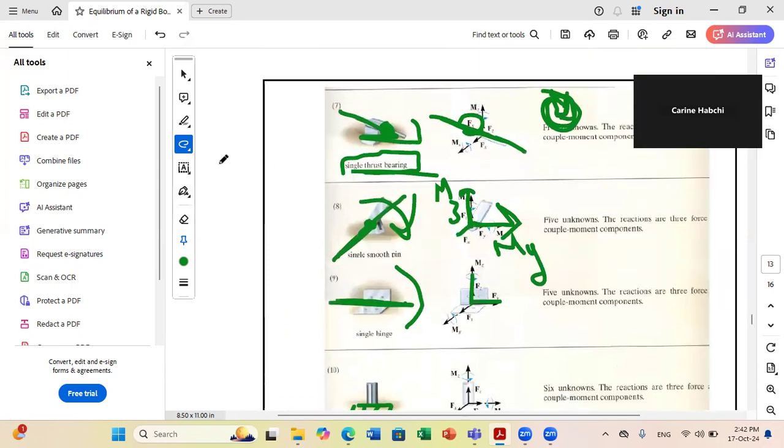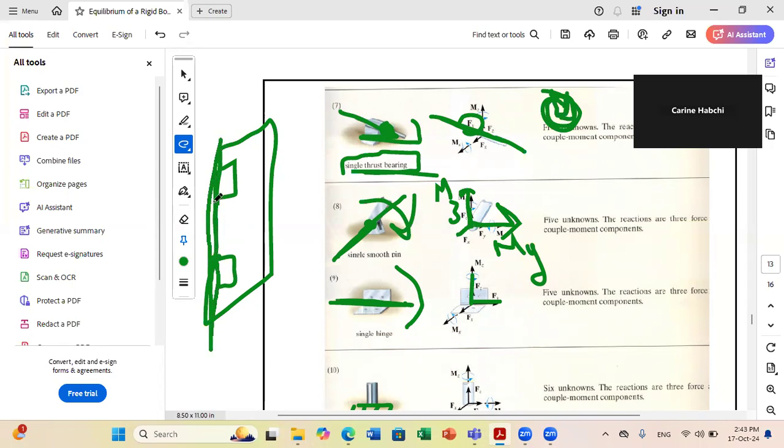Let us consider the door. You have a door. Okay? If you look at the extremity of the door you will see the hinge. Okay? You have these that you put along this direction to support your door. Your door, because of these connections, can only rotate about the vertical axis, right? Since you can rotate about this axis, this means that there is no moment reaction about this axis.